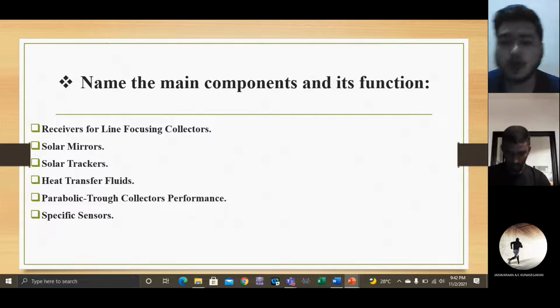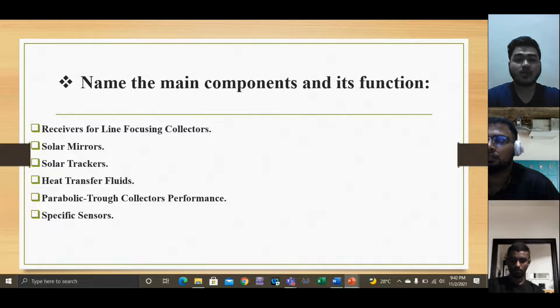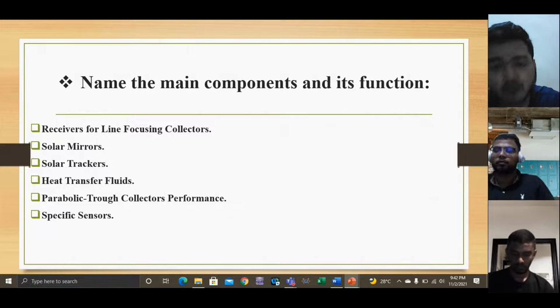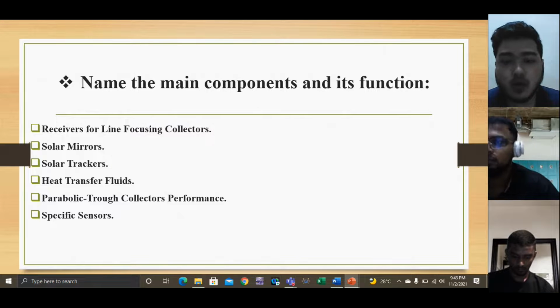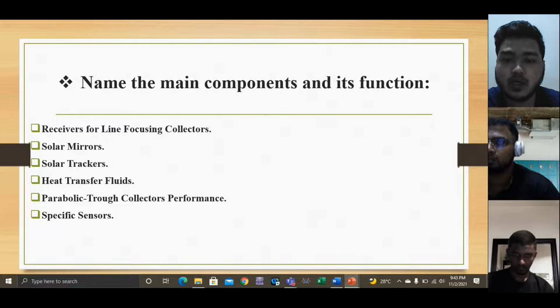they absorb the concentrated radiation at the focal line of parabolic trough and linear Fresnel collectors. The draft standard covers receivers with a central absorber tube and glass envelope, specifying the relevant product parameters and tests. The main requirements are good overall absorption properties, low thermal loss to the ambient, Q loss, and durability for at least 25 years of daily operation cycles and outdoor weather exposure. It's a good component for this project.